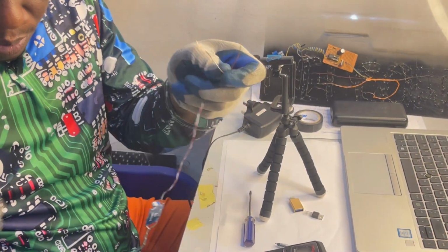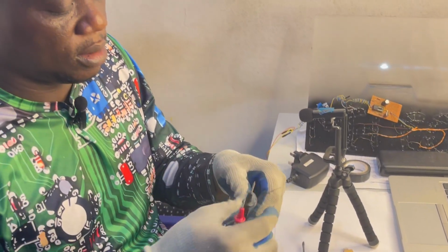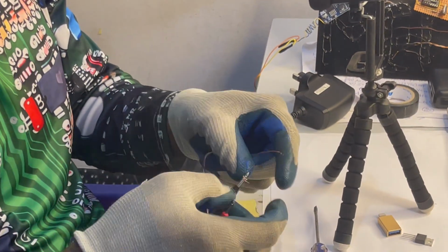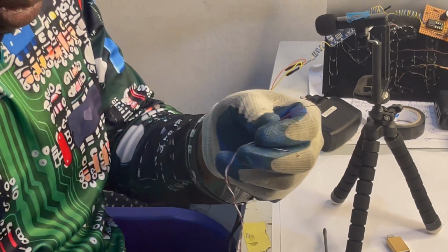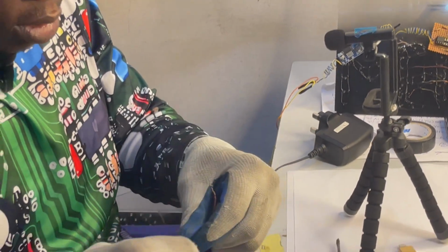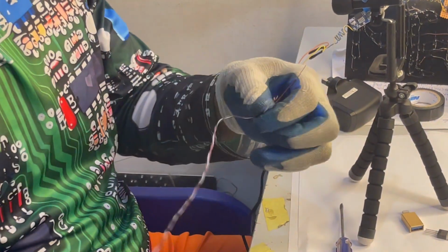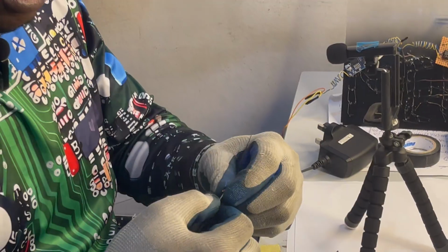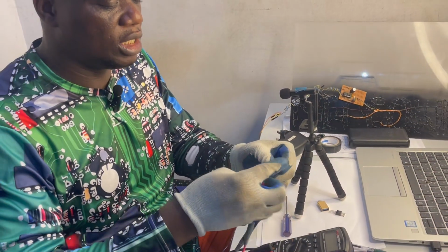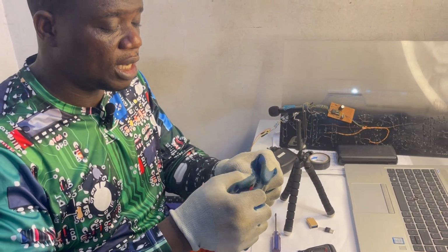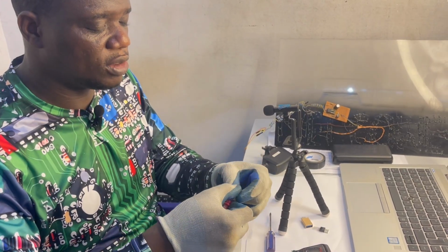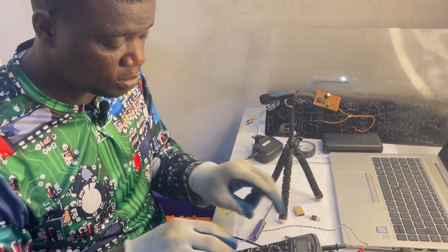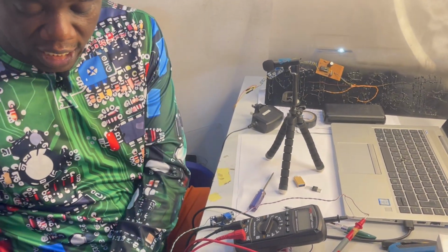I take my meter probes. What I want to do is reduce the voltage to 5 volts, because you can actually supply up to 36 volts to this LM2596 and it will take it. But what matters now is that you need to step it down to what you want. In this case, I need 5 volts. I don't need 24 volts. I don't need 12 volts. You will spoil the whole design. Your design will get damaged. This is a 24-volt adapter.